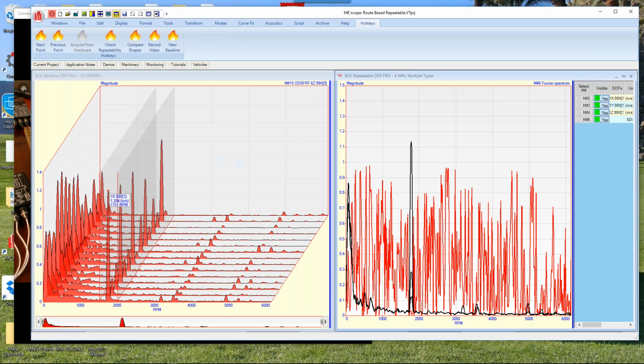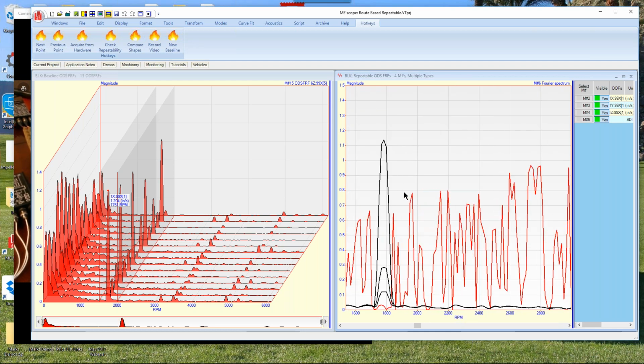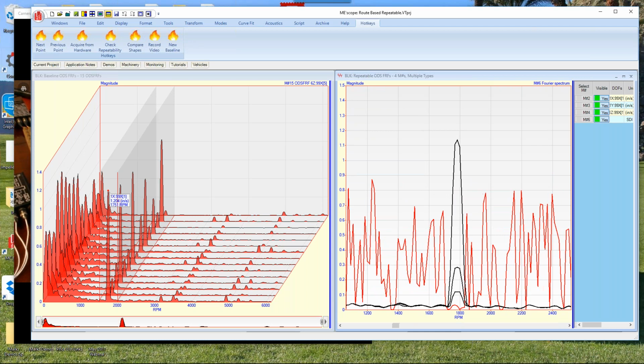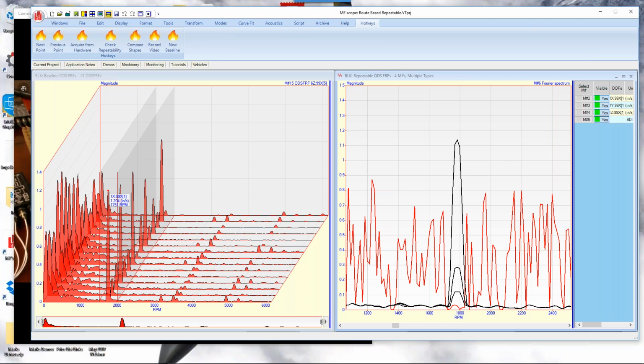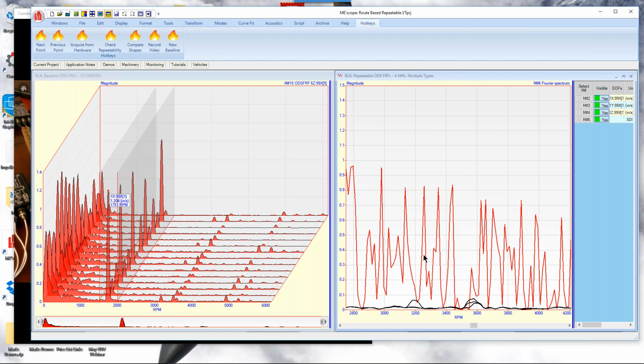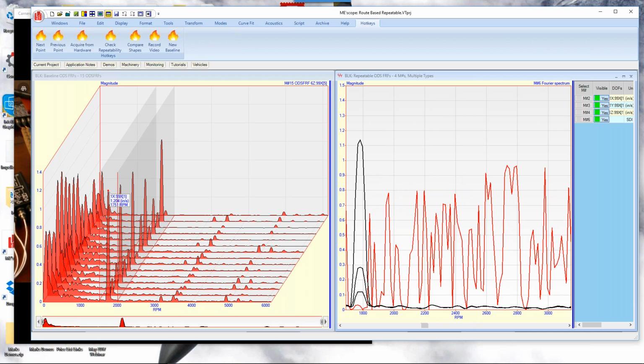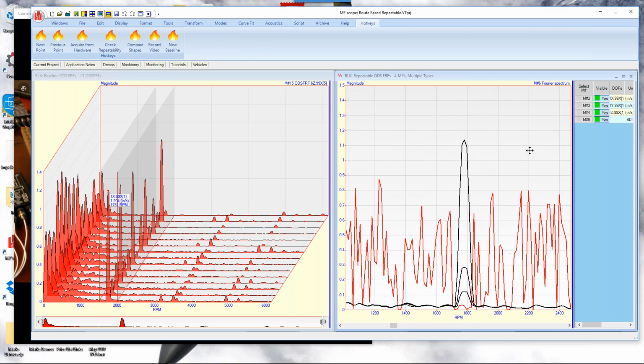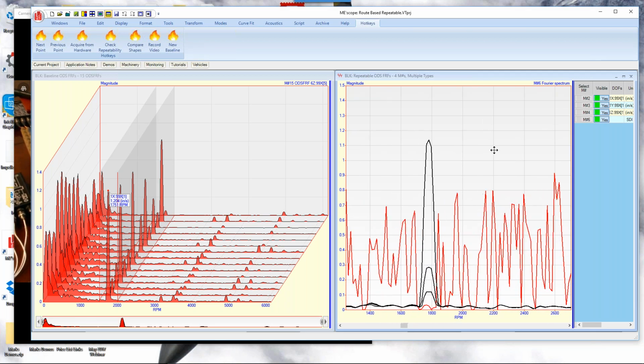And now let's zoom in here around the running speed and see what we have. Oh, look at that. See, the red values are way down here, almost to 0. So what it's telling me is that at the running speed, I made the wrong measurement. And here's the second order again, very poor. And the rest of the values are because of the random noise in the measurements. So there is what I wanted to show you.